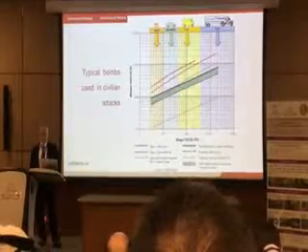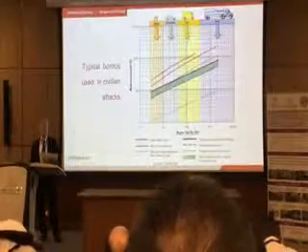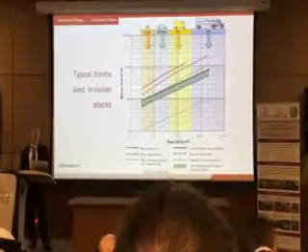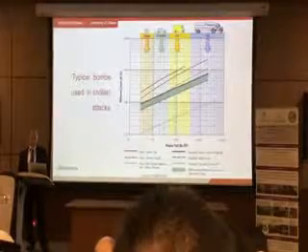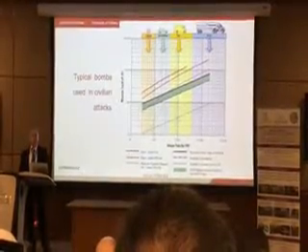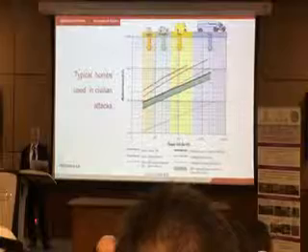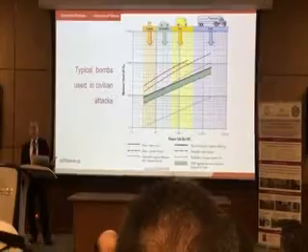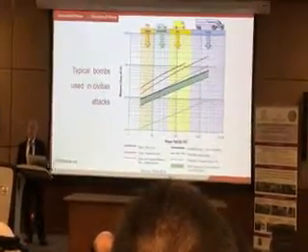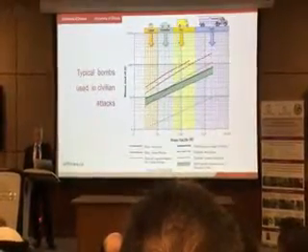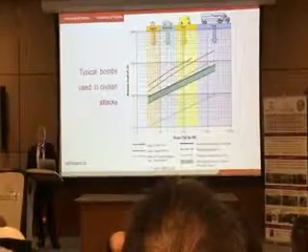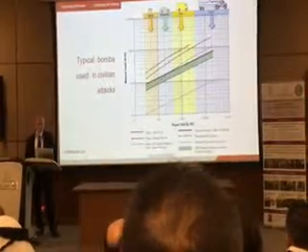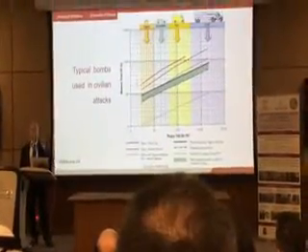If we were to take this yellow category van, so this is a 500 kilogram bomb, 1,000 pounds, and then if you provide it at 10 meters, the dotted line shows you that structural damage can occur, like columns can fail. So 500 kilograms at 10 meters is enough to bring building columns down. Or if you keep increasing the standoff distance, here this grayish green shows you 120 feet, right?